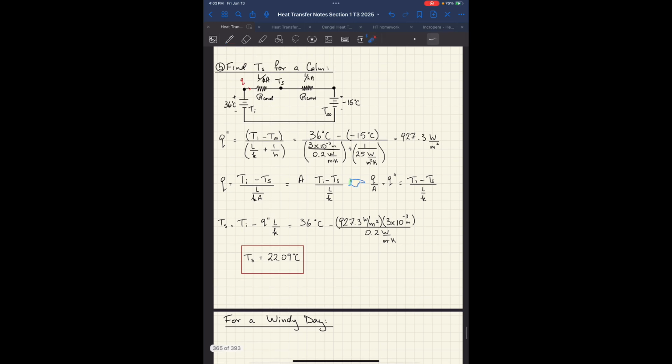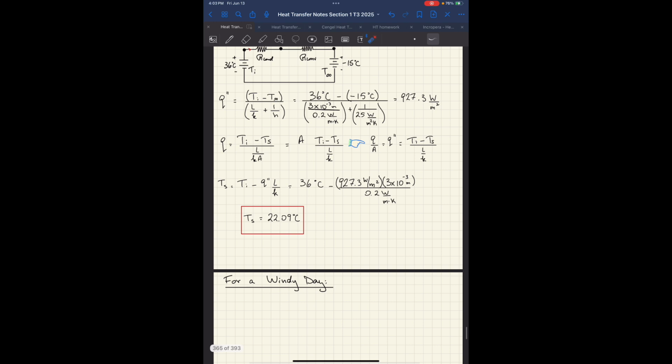So we did it, this voltage divided by this resistance. Because this is a series circuit, this current is the same everywhere. So I could actually have done Ts minus T infinity divided by this, and then solve for Ts. Same business. You get exactly the same answer. If you look at the previous solutions for the final review, you'll see I did it that way.